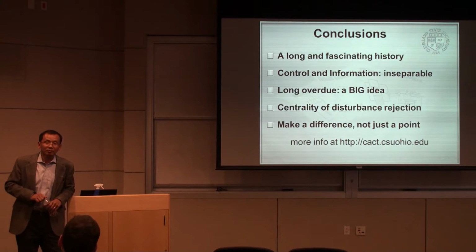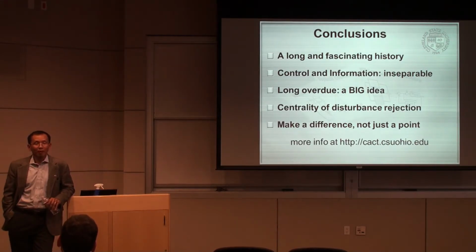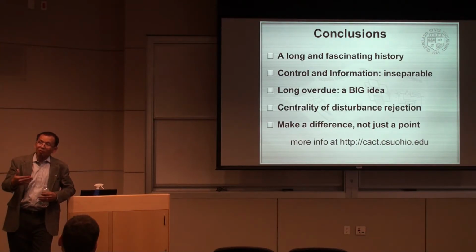So, do we have any other dominant dynamics cases? It's multiple integrators and oscillator. Is that it? Or do you use some knowledge of dominant dynamics? That's an excellent question. Sometimes you do know the dynamic structure. Part of that is already known. Why not take advantage of it? That can be taken into consideration in the structure of the state estimator. If you know the dynamics, you can put it in.